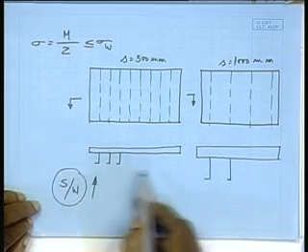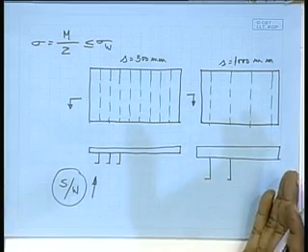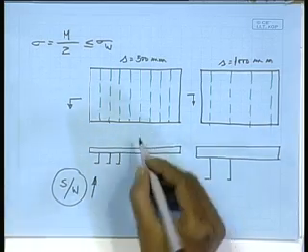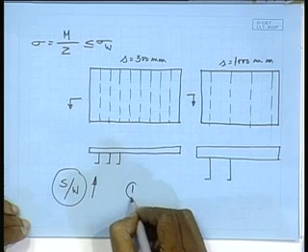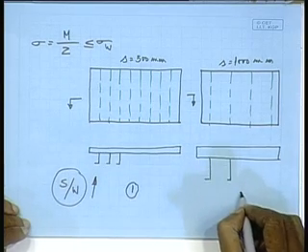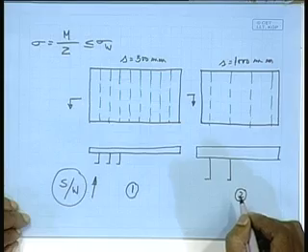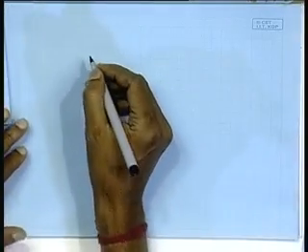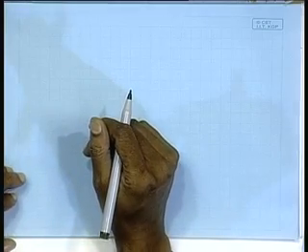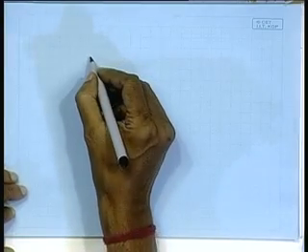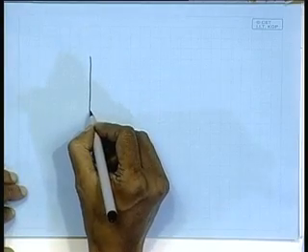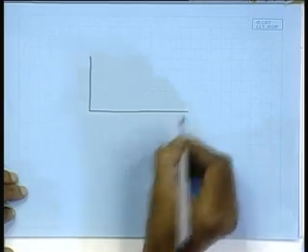Right? Now, I cannot say offhand whether option 1 gave me a higher value of this, or option 2. So, in fact, for doing it more systematically, one should do it for various frame spacings, right, and then plot a curve and see where you are getting the minimum.